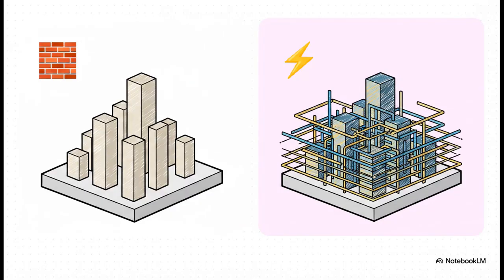Now, the industry kind of splits this whole construction job into 2 big phases. First up is the front end of line, or FEOL. This is where you build the actual transistors, the capacitors, all the active components. These are the buildings in our microscopic city. After all the buildings are in place, then comes the back end of line, or BEOL. And this is all about laying down the metal wiring that connects all those buildings. This is the city's roads and power grid.